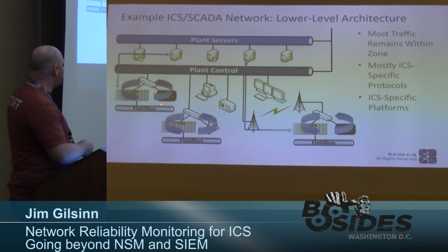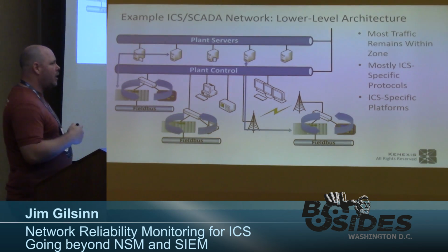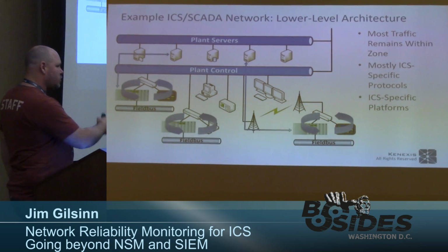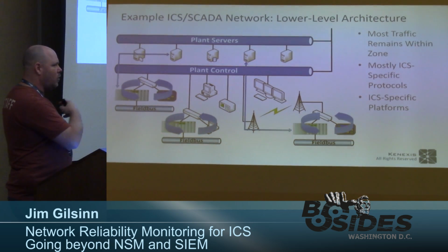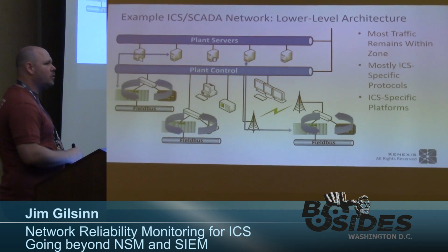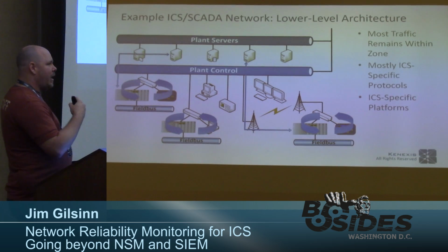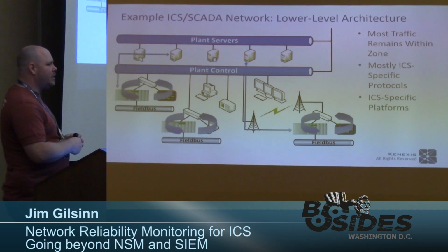And you're also dealing with very dedicated ICS protocols. These are protocols that are designed to do controls at that level. So there's Ethernet IP, there's Modbus, there's Profinet, there's a whole list of different control protocols that are out there that use Ethernet as a physical media. And some of them use different various levels of the TCP stack.